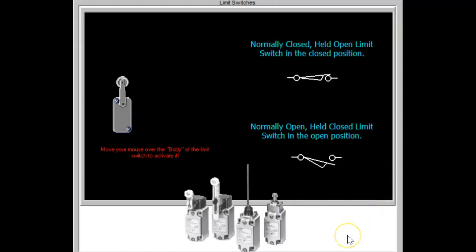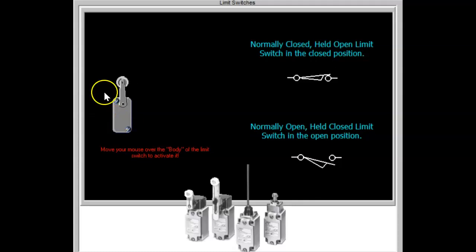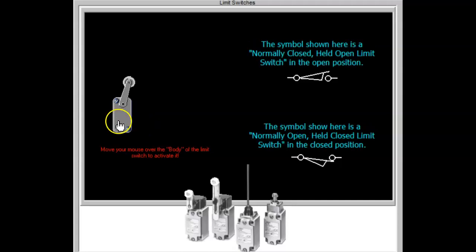Automatic operation of today's machinery requires the use of switches that may be activated by the movement of the machine. The repeated accuracy of the switches, reliability, and the response of the switch must be practically instantaneous. The operating force, stroke, size, and mounting are critical factors in the choice and installation of limit switches. This is in part due to the mechanical limitations of the machinery. It is also essential to carefully match the electrical rating of the switches with the loads to be controlled.